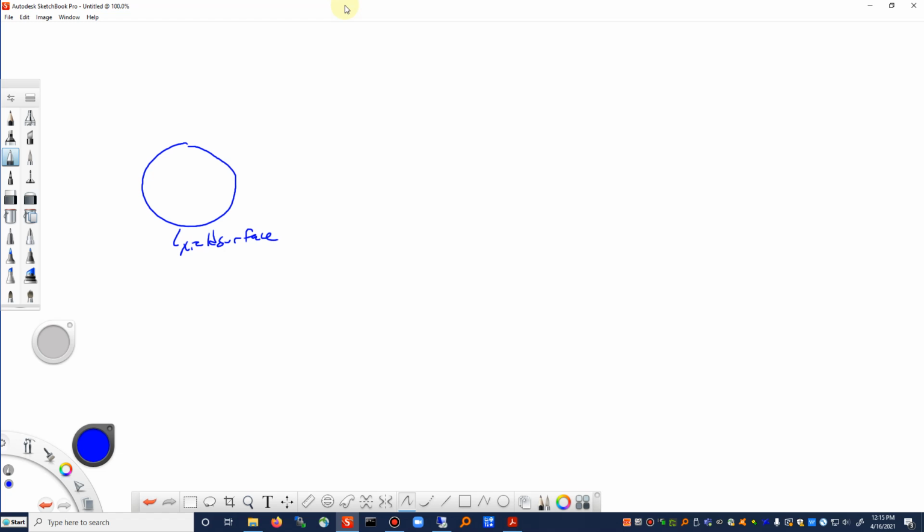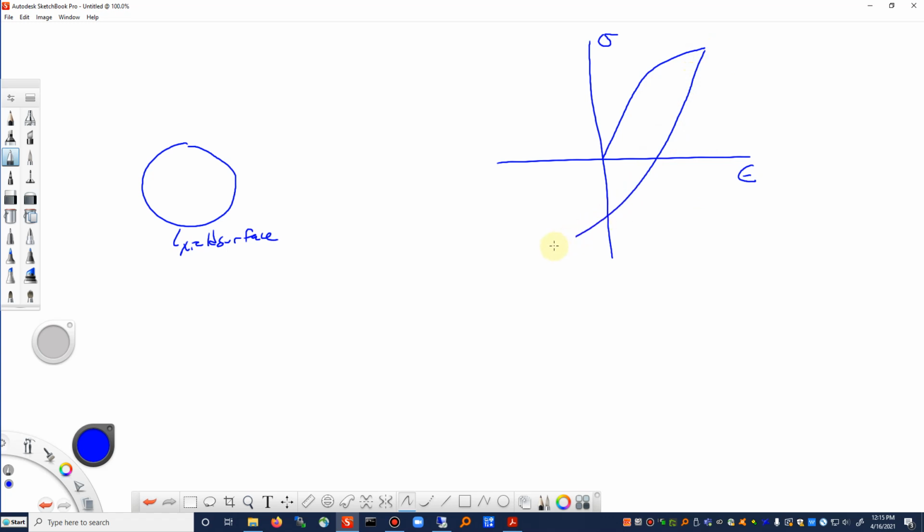Okay, so how does this relate to what we know about uniaxial behavior? In particular, cyclic behavior. So if we were to look at our stress strain curve, we know that when we first load it up, it might do something like this. And then when we unload it, we get a nice hysteresis branch. And we reload it, we get a nice, smooth looking hysteresis curve. And it plots in that shape. By the Bauschinger effect and Masing's hypothesis, this region would be approximately a size of 2 sigma yield.